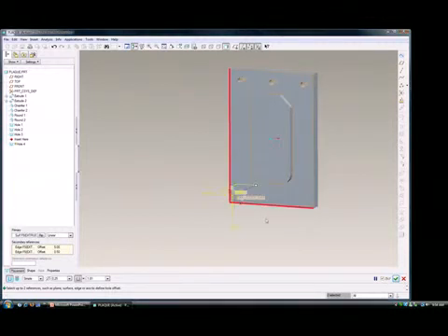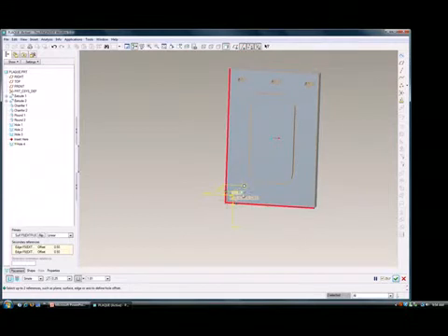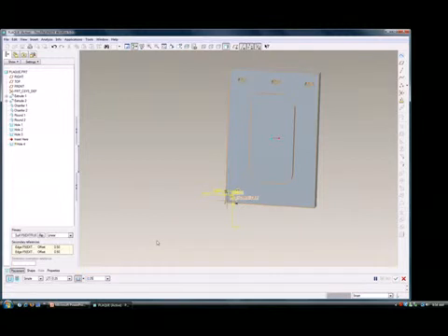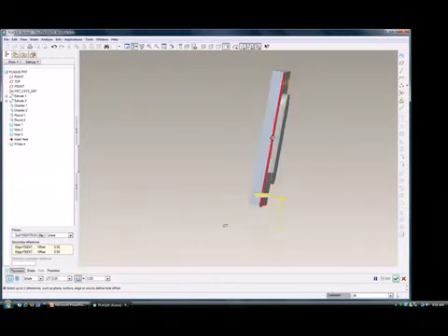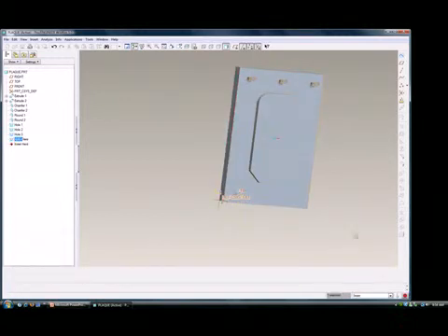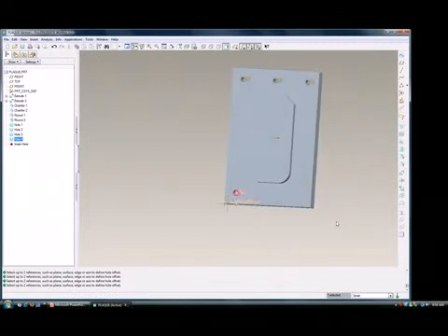Okay, and then the diameter is 0.25, and the depth now is actually the depth here. Specify the exact depth here. It's actually 0.25. Okay, so hit the confirm button, middle click button. Okay, looks good. Now for the very last hole, so again put it on this surface,